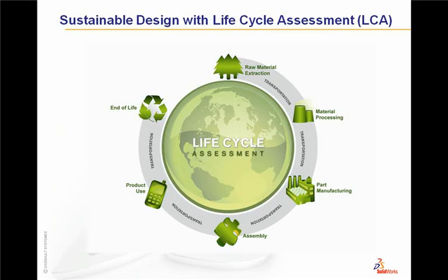Now, there are several methods used in sustainable design. SolidWorks Sustainability uses the most popular of these, which is called the Life Cycle Assessment, or LCA. LCA is used to understand the environmental impact of the design, starting with raw material procurement to product manufacturing to product usage, and finally to product disposal. LCA quantifies all emissions across each phase of a product's life and is defined by the ISO 14040 standard.